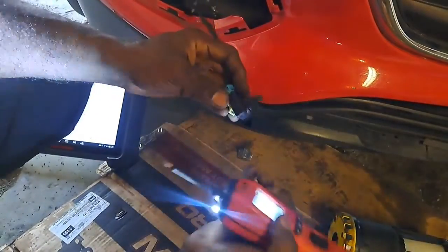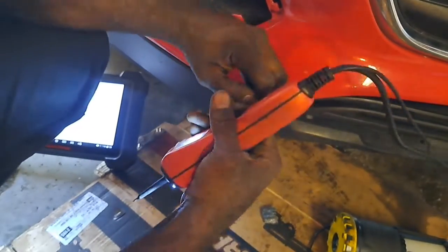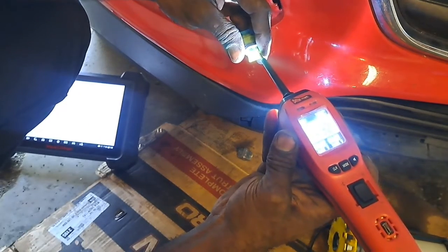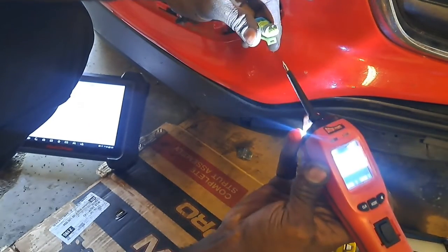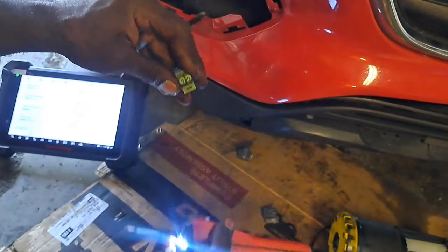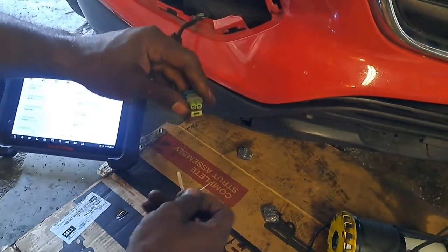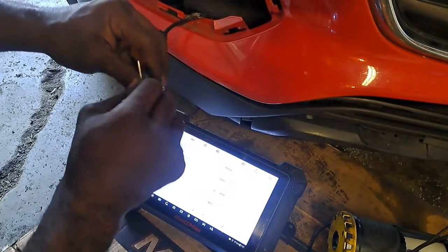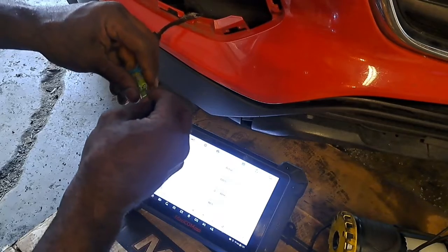Before, the power probe responded to the signal wire as the ground. So we got our 5 volts. Yeah, it's doing the same thing as it was up there. Let's try jumping the sensor and see if the data changes, because the sensor may have just been compromised from the collision.